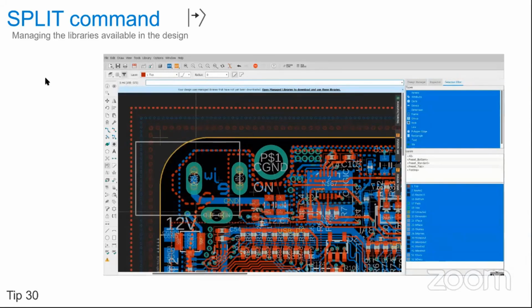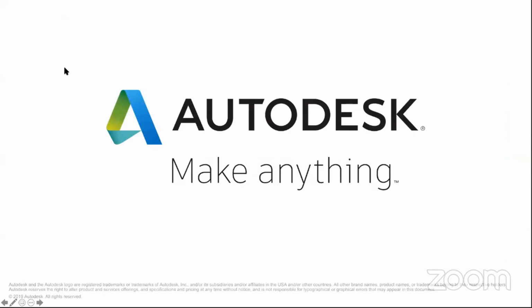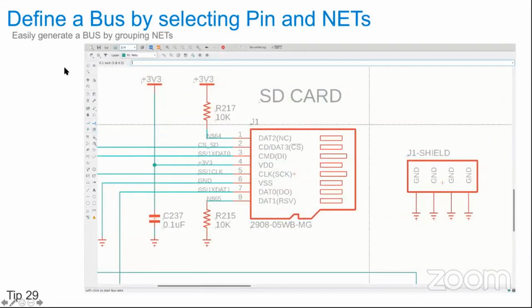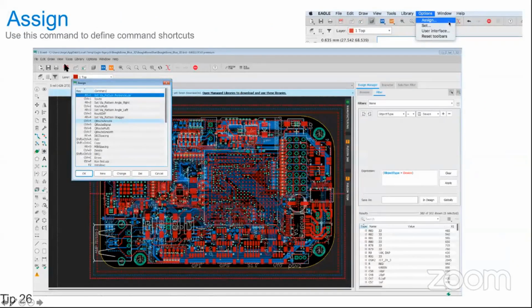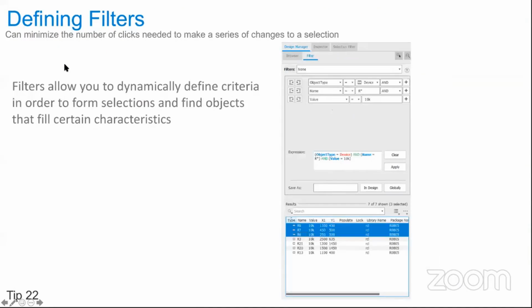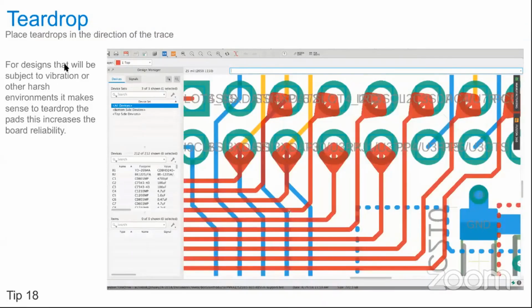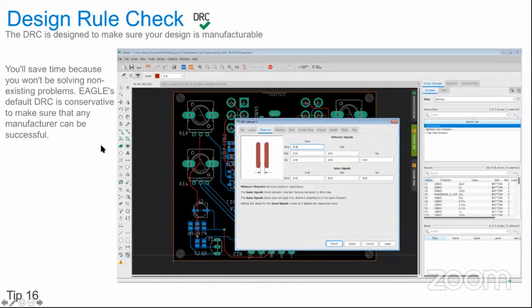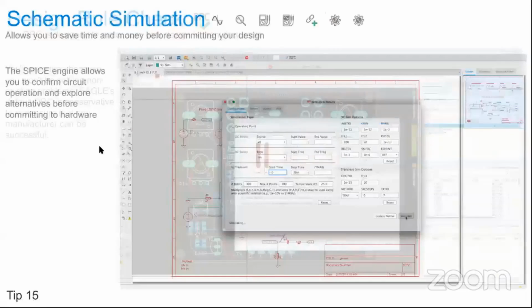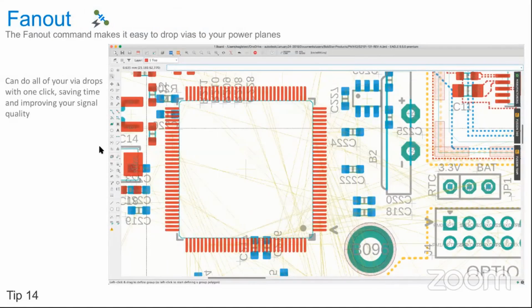Yeah, so just to finish off that question, the length matching, assuming again that the drivers, the original circuit, are in phase. If you match lengths, then the phases should match as well. Again, as long as there's no changes in impedance and the traces are identical. So like I mentioned, we'll go over that in another webinar. But in most situations, if you length match, you'll phase match as well. Only if you make changes in width and alter the impedance of the traces will there be a difference there. Thank you, Jorge. Appreciate that.